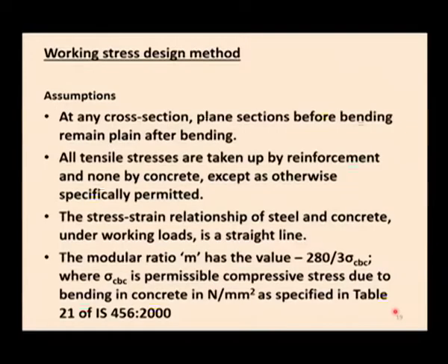We all know that concrete is very strong in compression, but weak in tension. So, in the case of a beam, when it is subjected to any kind of force and is deformed, the layers above the neutral layer are subjected to compressive stresses. All the compressive stresses are entirely taken care of by concrete, since concrete is very strong in compression. When you go to the portion below the neutral layer, it is subjected to tensile stresses. Here the concrete is very weak in tension. So, that is why we have provided an alternative material to resist those tensile stresses, which is called steel reinforcement.